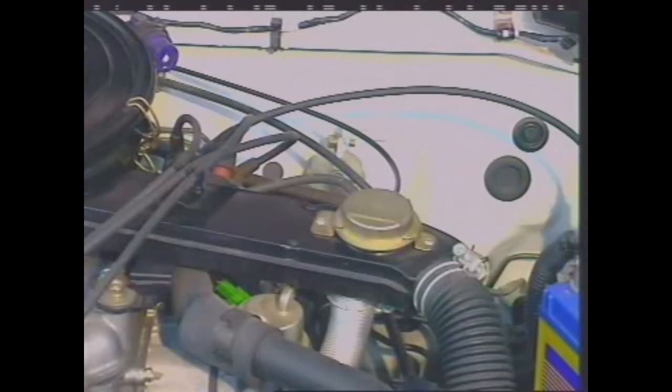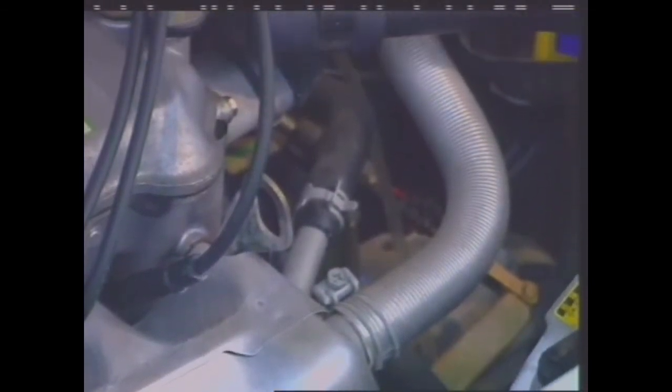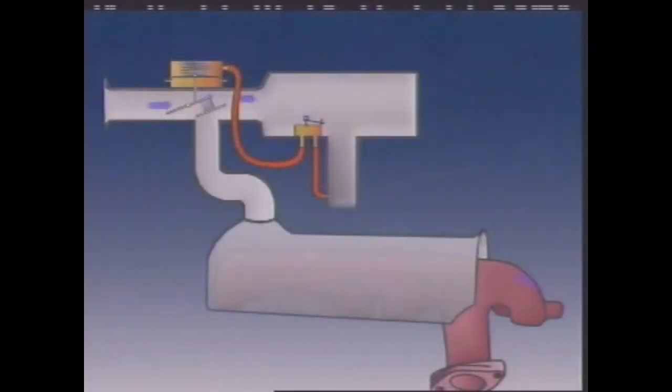Carburetors meet emission standards by maintaining accurate mixture control over a full range of engine conditions. To achieve this, most carburetors require an air supply at constant temperature. A heated air inlet system uses hot air collected from near the exhaust manifold and mixes it with outside air. One control system uses a temperature-sensitive valve inside the air cleaner. It operates a flap that blends the hot air with cool air, so that the carburetor receives air at about 40 degrees Celsius, regardless of outside air temperature.